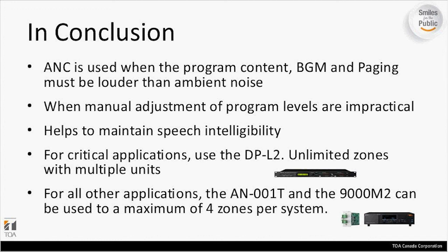The unit helps to maintain speech intelligibility because you can set the level that you want for so many dB over ambient and it'll maintain that as the sound goes up and down. As the noise goes up and down in the environment, it'll adjust the output volume.